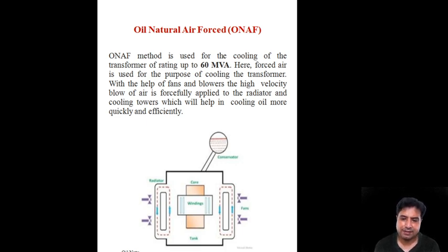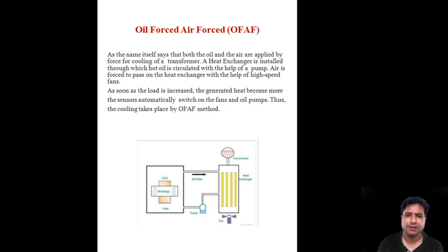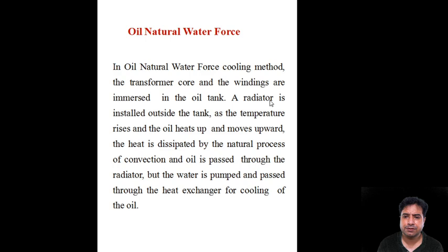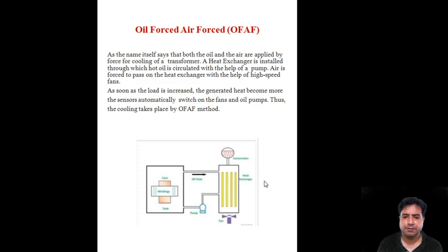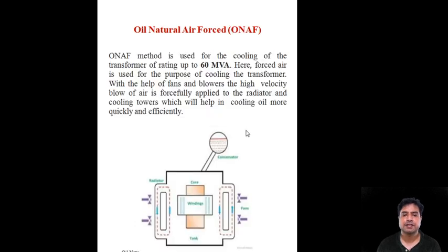So in this case, essentially the difference between the air natural and air forced is that here we are employing mechanical means for blowing air at a certain velocity. And if you see the rating of transformers, it can be used up to 60 MVA.